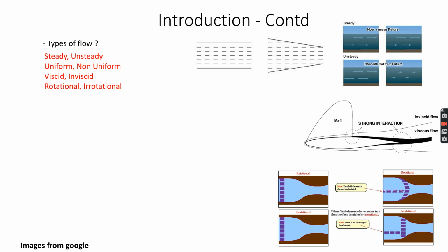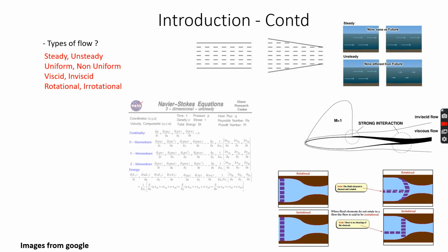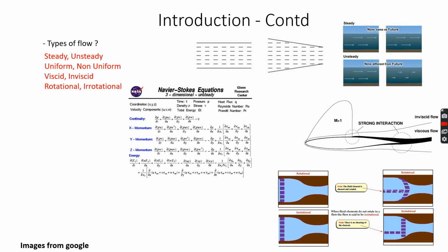You could be looking at it on the internet. And so, as I mentioned earlier, the Navier-Stokes equations, which are the set of continuity and momentum equations, are the set of four equations for incompressible Newtonian fluids. As you can see over here, these depend upon time and also on space.